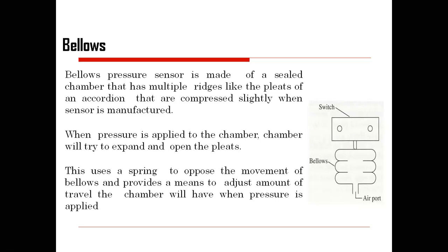So what is the means of exhaust? It is very simple: when we apply a pressure as an input, created due to the heat, automatically when it reaches its threshold level, that whistle, or you can consider it a pressure switch, will become open and it will try to exhaust the pressure that has been created in the cooker.